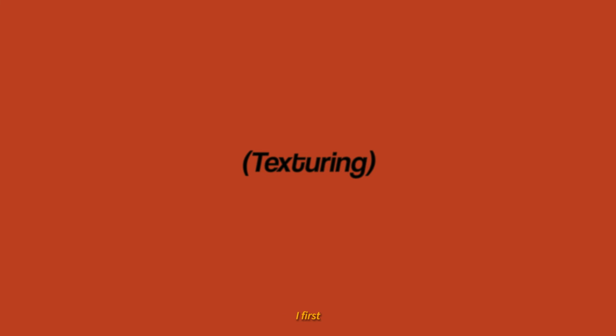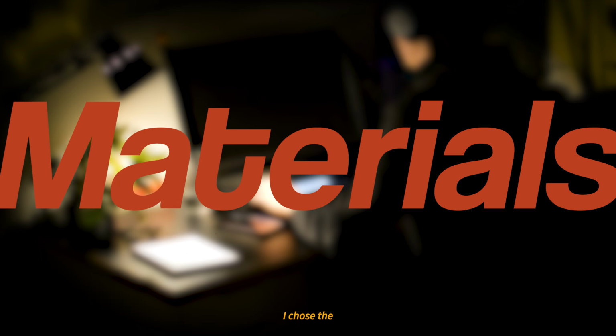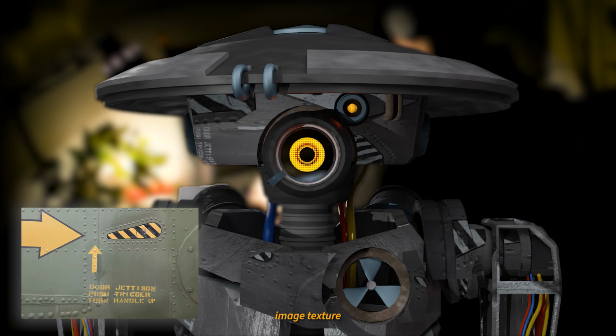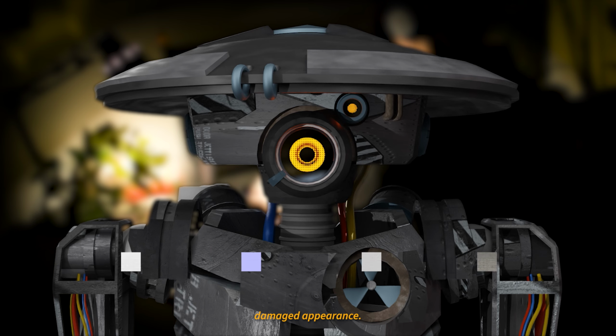In texturing, I first defined a color palette that complemented the mood of my project. For this, I chose blue, orange lights, and 2 different grays for mechanical elements. Next, I chose the material properties of individual elements, with the majority being metallic or plastic. I used an aircraft door image texture to add detailed variation and decals to my character, making the robot appear more constructed from scraps rather than new and original. To add realism, I used a concrete image texture to add wear, rough areas, and overall damaged appearance, using displacement and a bump node with a normal map.